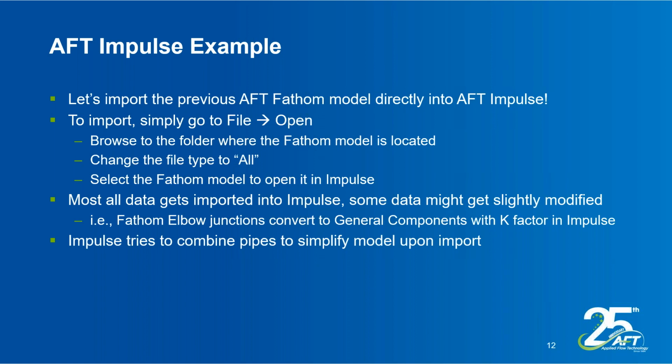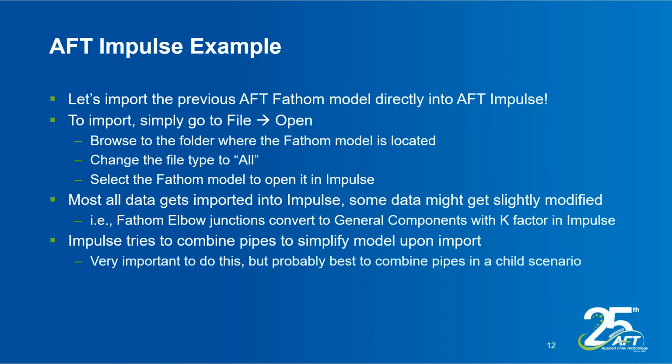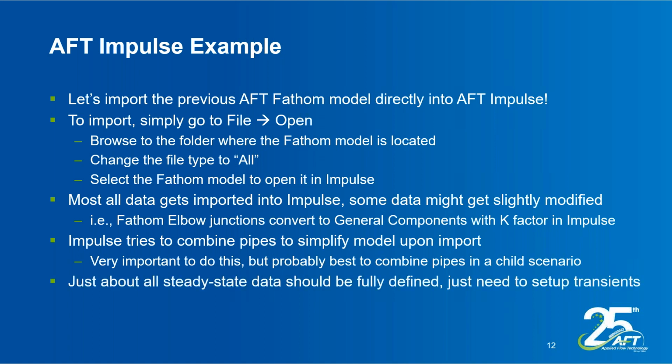Another thing that Impulse will try to do is to combine pipes to simplify the model upon import. That's a really good idea, and if you watch one of our video tutorials on pipe sectioning, that'll illustrate why you'd want to combine your pipes. That's outside the scope of today's webinar. One of our videos illustrates that, and you can find it on our website. But it's probably a better idea to combine the pipes in a child scenario.